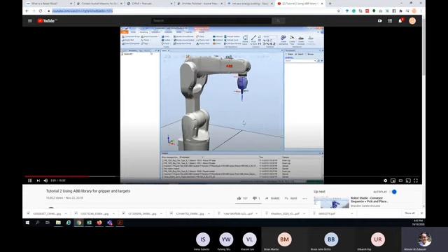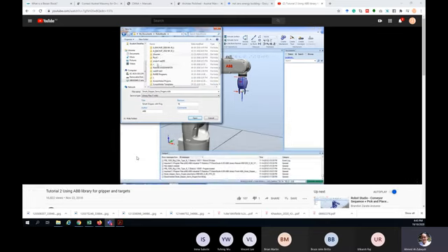You can have the same robotic arm and the same gripper, which is available in the library, but make your own CAD model as part of the novelty. Import the CAD models into Robot Studio and just pick and place the parts. This can be another example. Or just have a box, or a cylindrical shape, and put one of the welding devices available in the library as the end effector, and try to simulate doing the welding around this spot.